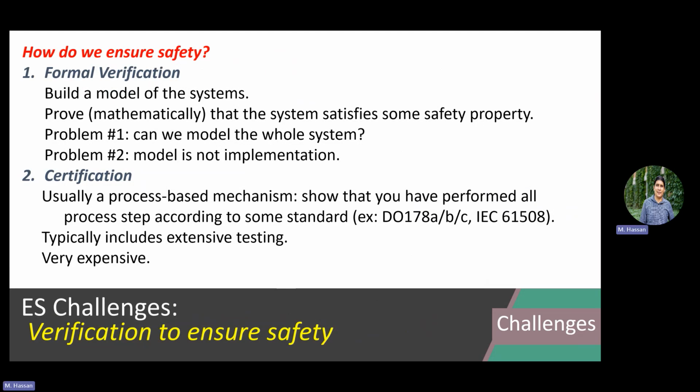So how do we ensure safety? What do people really do in industry to ensure safety? The first thing is formal verification, right? What we mean by formal verification is simply that the certification standards in automotive, for example, tell you an airbag task is the highest critical, or engine control is the highest critical. You need to write math proofs, in fact, to ensure that under all worst case scenarios, you will never exceed, for example, your deadline, right? There is a formal proof, usually produced not through paper and pen but through automated tools, right? There are commercial automated tools for this verification that simply give a mathematically backed proof to the certification authority that this task is totally safe under all scenarios.